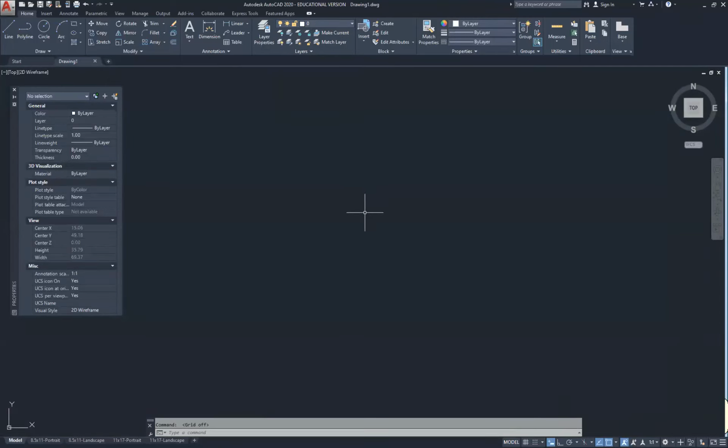And the length can still be adjusted because I hit the tab key. But if I had punched in on length, it wouldn't change. Tab, let's say 40. Hit tab. Now you can see it's locked at that distance, and I can set the angle.